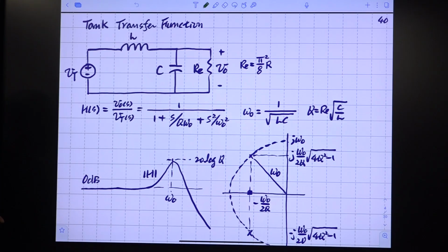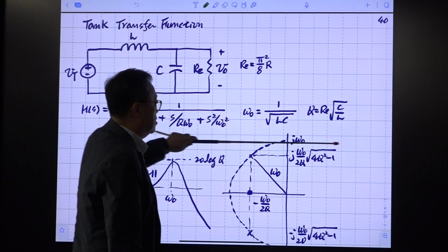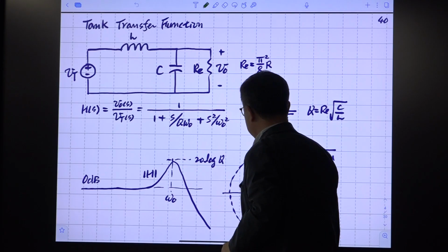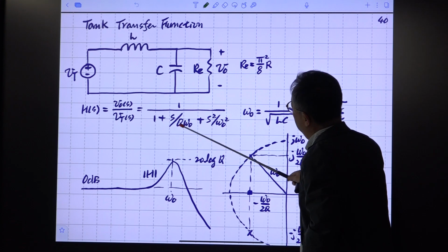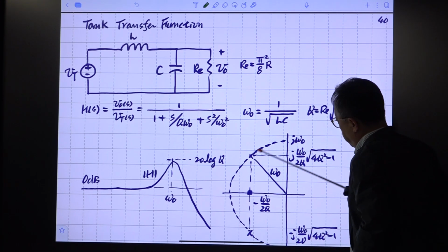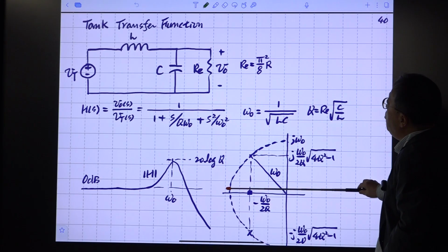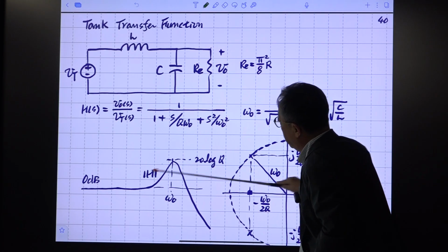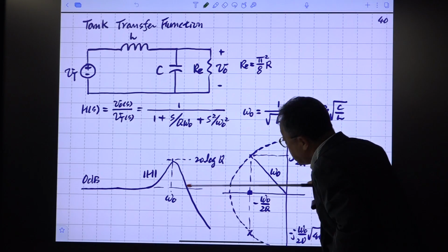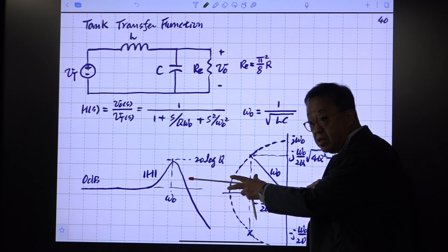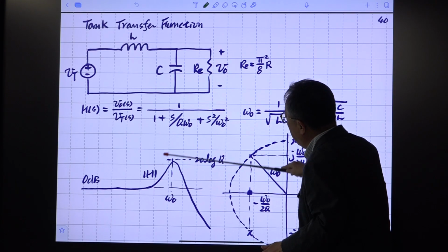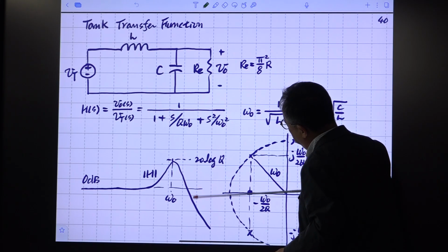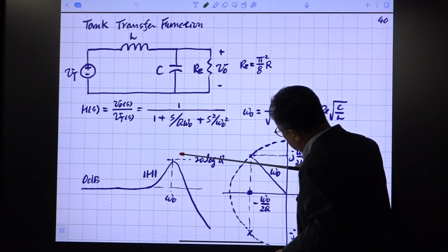Then this looks like the inverter. The result remains the same. And this is the standard second order equation with omega_0 here, and this is the Q of this resonant tank circuit. So from this Q and omega_0 information, we plot this. This is in the omega_s plane, and this is the Bode plot of this transfer function. This low pass filter peaking is very large, so we are using this part as the band pass filter. We are taking advantage of this high Q resonant low pass filter.